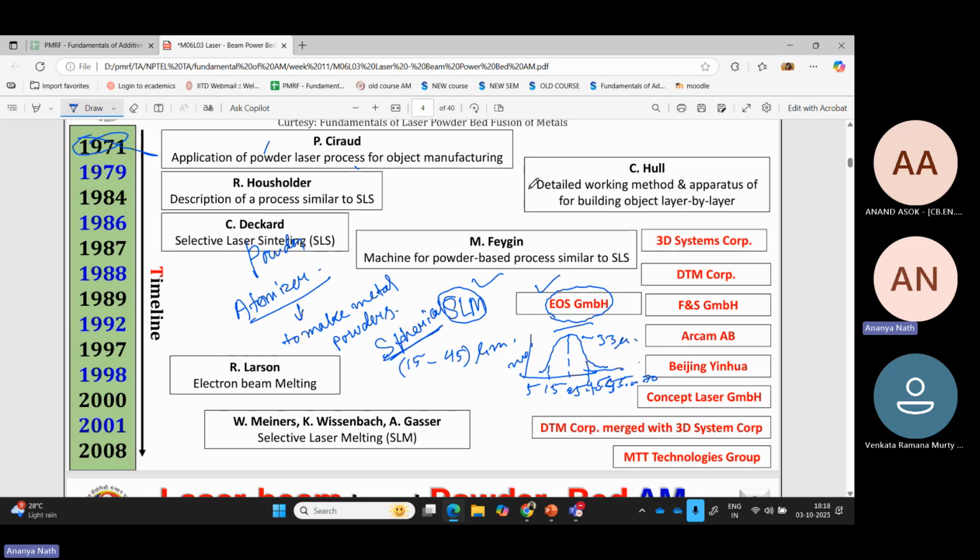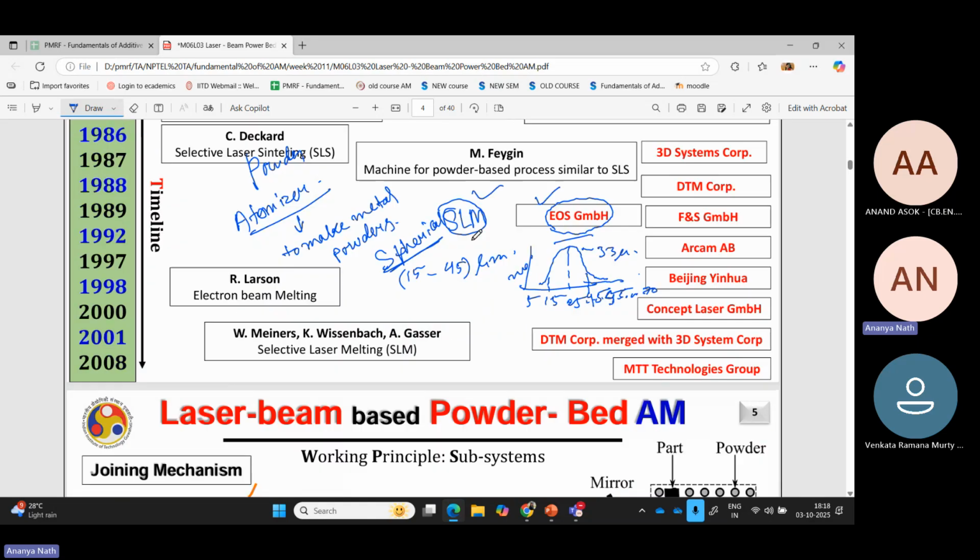For DED, we use the powder atomizer. Then the machine itself is very costly. So as the machine is costly, the printing is very costly. So these days, people are trying to make their own homemade PBF systems to minimize the cost so that they can get the benefit of PBF over DED, but at a lower price. So this is the state right now.